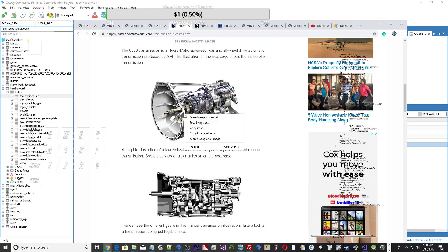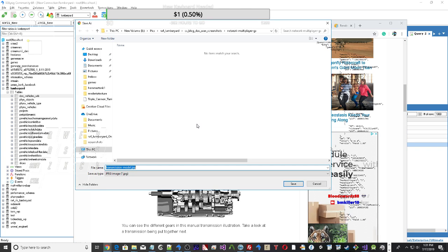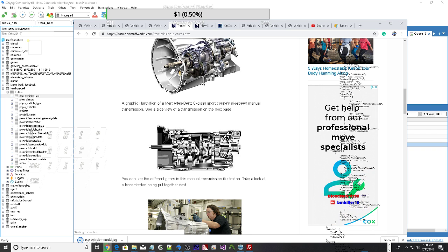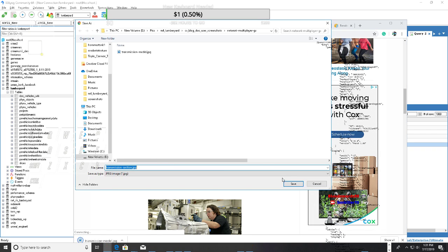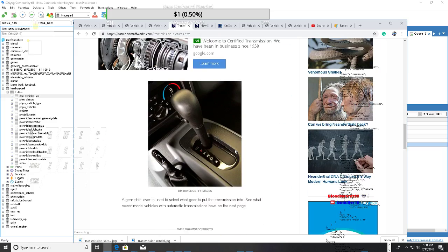Set up the wheels. PxVehicleWheelData wheels[PX_MAX_NB_WHEELS]. Set up the wheel data structures with mass, moi, radius, width.